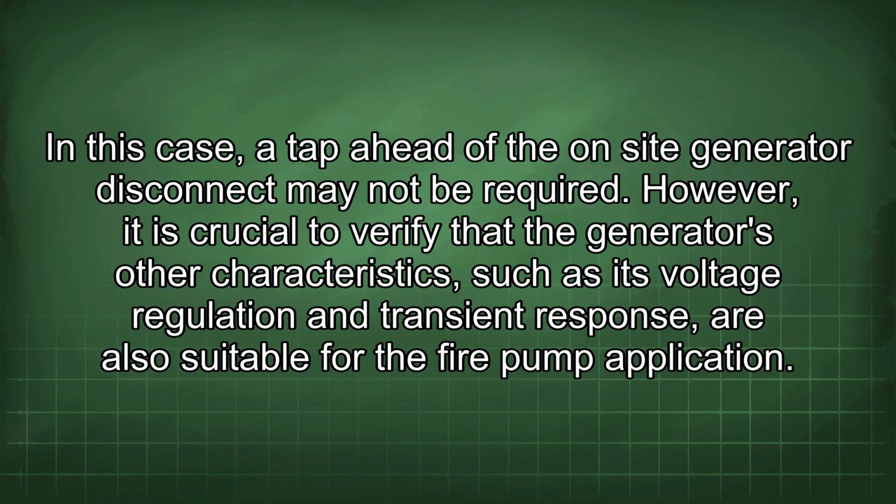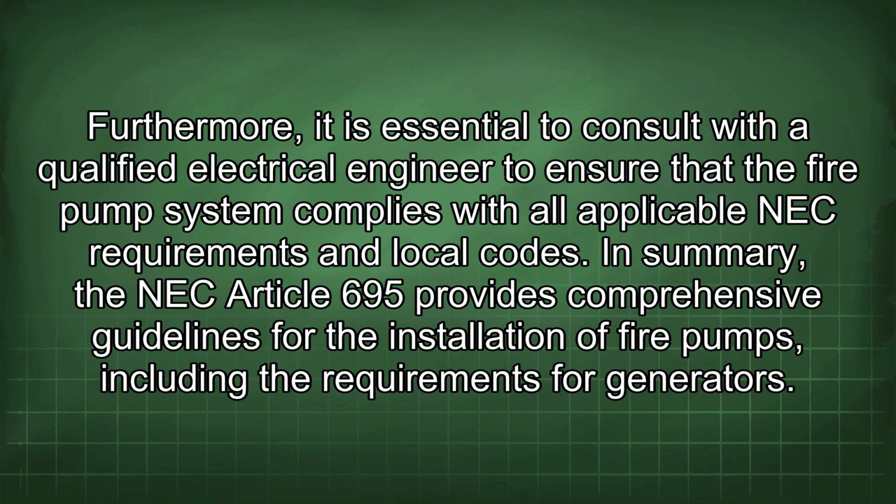However, it is crucial to verify that the generator's other characteristics, such as its voltage regulation and transient response, are also suitable for the fire pump application. Furthermore, it is essential to consult with a qualified electrical engineer to ensure that the fire pump system complies with all applicable NEC requirements and local codes.